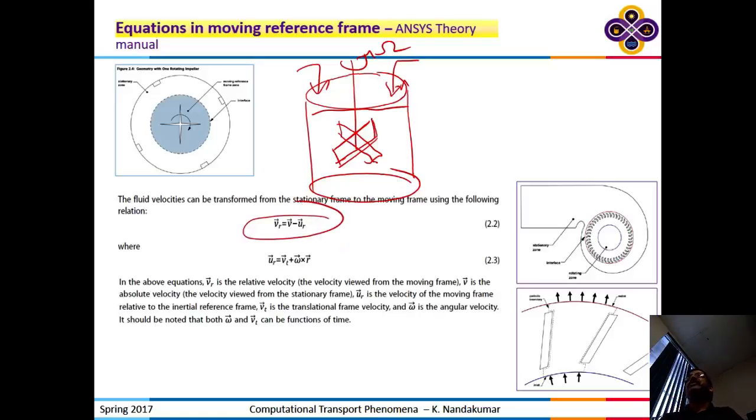How that is done. Okay, so translating the reference frame in which we wrote the Navier-Stokes equation in a fixed laboratory reference frame, we can move that to any other reference frame that we want. And if you are able to do that, then we can solve the problem in that moving reference frame if it becomes simpler, but reconstruct by transforming back into our laboratory frame. So we go from laboratory frame to a moving frame, solve the problem in the moving frame, come back to the laboratory frame for interpretation. Yeah? You just have to change the coordinate systems.